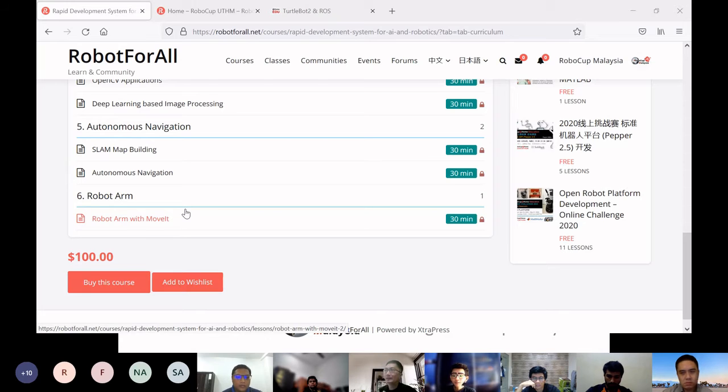But for the rest of you without the hardware, I will also show you how you can do it with the Gazebo simulation. So this is for the navigation. And lastly, we have the arm. On the Jupyter Robot, we have 5-degree or 7-degree arms. We have both models in Jupyter Sim that you can run. I'll show you one very brief example of how we integrate these models into MoveIt, and then you can do some MoveIt development. MoveIt is the planner in ROS for you to design and develop your arm manipulator.